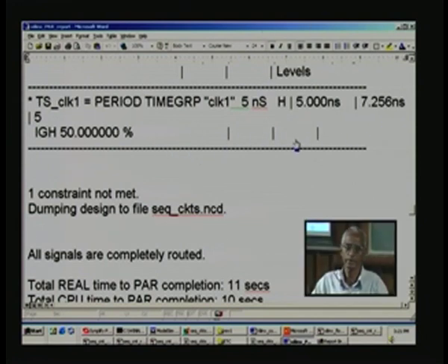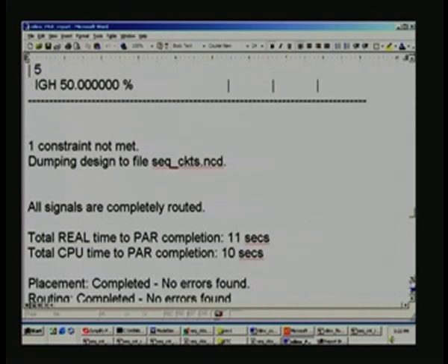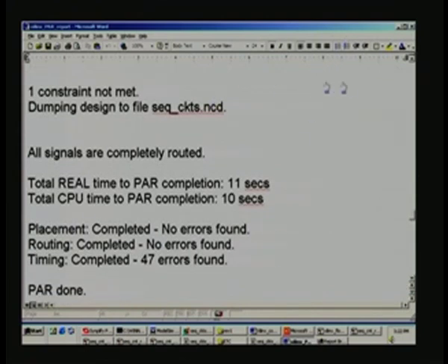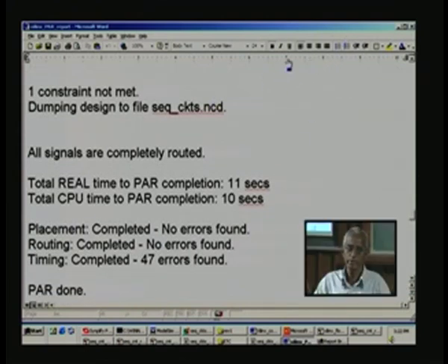Even here, in real practice, people have reported an even better result than what Xilinx's place and route gives. For example, it may be 10 to 25% better performance that you can get based on real experience. So what they give is a guaranteed speed of operation here. And normally, as I mentioned, if the design is quite huge, what synthesis will report will be a much higher frequency of operation than the place and route.